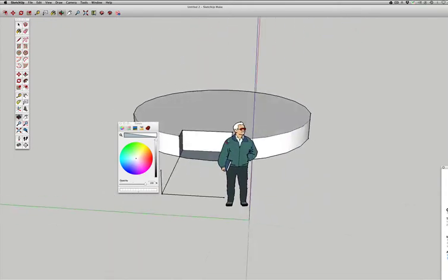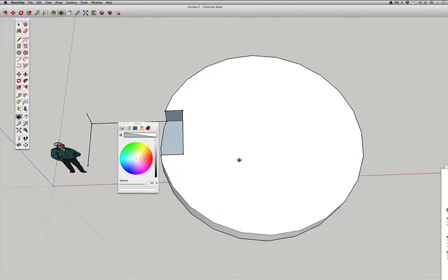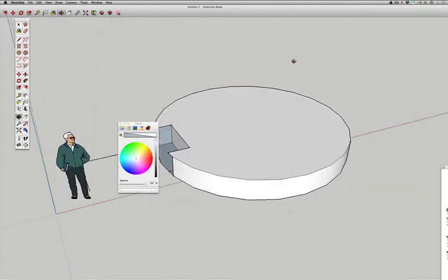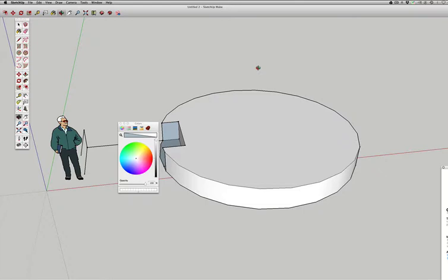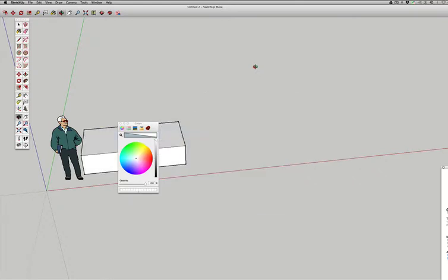So I cut a hole in that rectangle. I use the rectangle to cut a piece in it. See? There, it's gone. So you can do circles. You can push and pull the circles. You can drop the circles. Let me put this over here. I can put a circle. If I hit spacebar here, I hit C for circle.